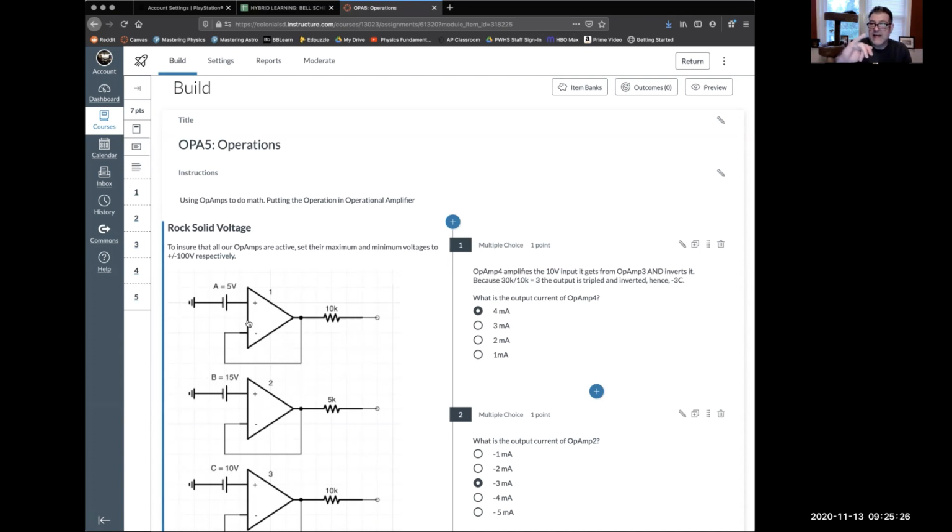In order to build this thing, when I choose an op amp by default in iCircuit, it does negative positive. Well, now where you go on the options for that, you can swap it so it's positive negative. And I set it up like this. I have this running around underneath. What this effectively does is turns the operational amplifier into a voltage source. Here's what I mean by that. It's basically a non-inverting amplifier with 0 amplification. So the output that I get here is exactly this input.